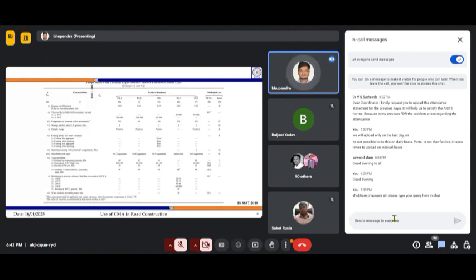Now this is the table that I have taken from IS 8887:2018, and here you can see the table which gives us the requirements: how you can check which grade of emulsion it is and what tests you can do to determine that. These are the physical and chemical requirements for the bitumen emulsion, and this is for the cationic type only, where the charge on the particle is positive in nature. So we check the residue on the 600 micron sieve.